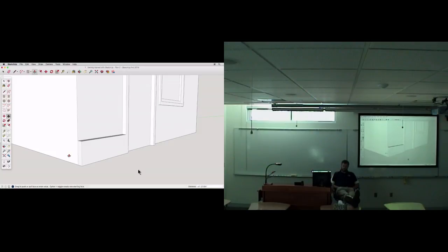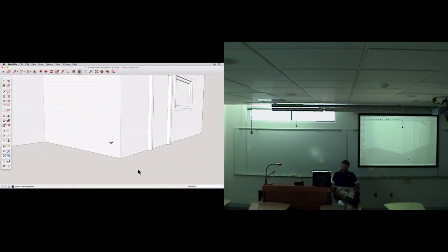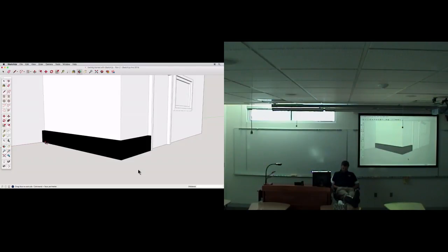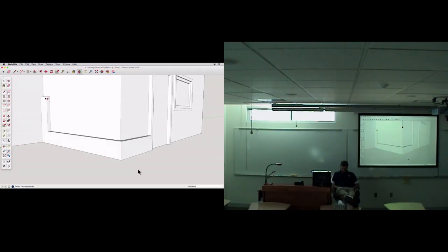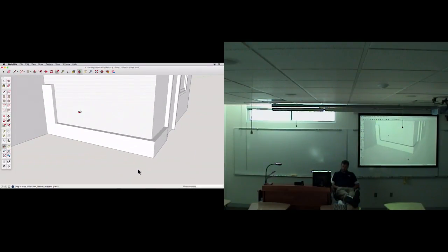Hit the Escape key to cancel the Push-Pull, or undo it. Then, select the Follow Me tool and click once on our trim surface. Pull along this lower edge, and it looks similar to Push-Pull, until you meet the corner and continue in a different direction. You can pull upwards or around the corner and follow any joining edges, and click to finish. The key to Follow Me is having a continuous edge to follow.